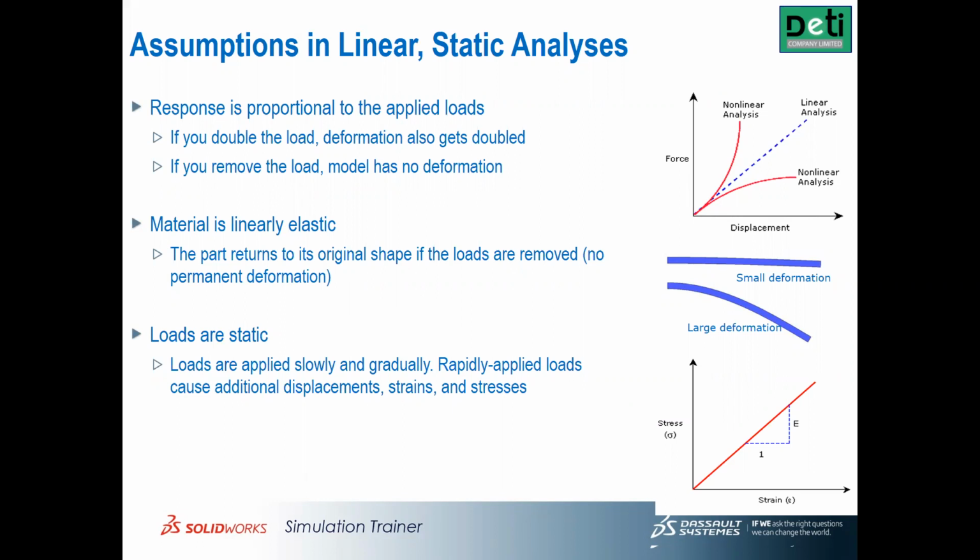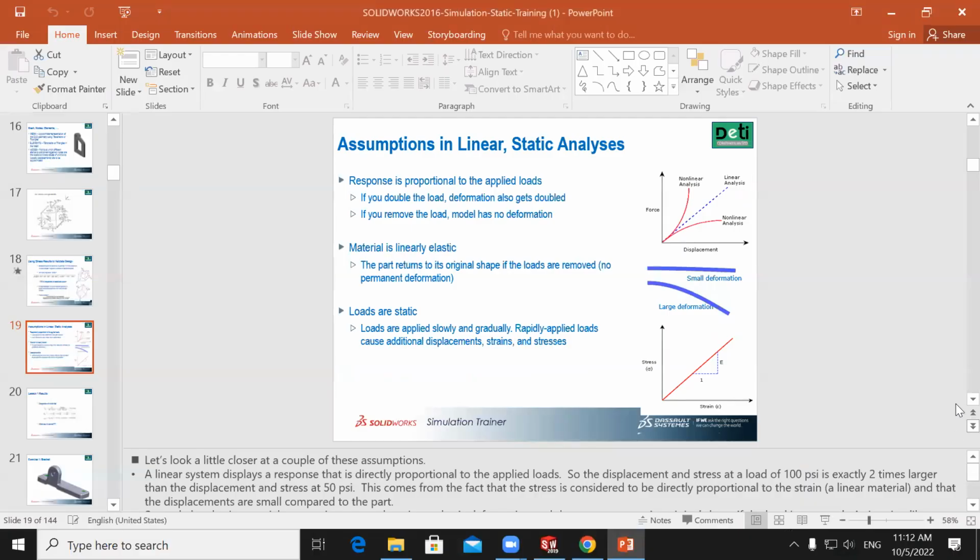Okay, and the program just asks whether you are trying to do large deformations or not. Then the property will be changed to another property, not in elasticity. But if you are concerned only about elasticity, we just say no. Just take it as a constant Young's modulus in that region.